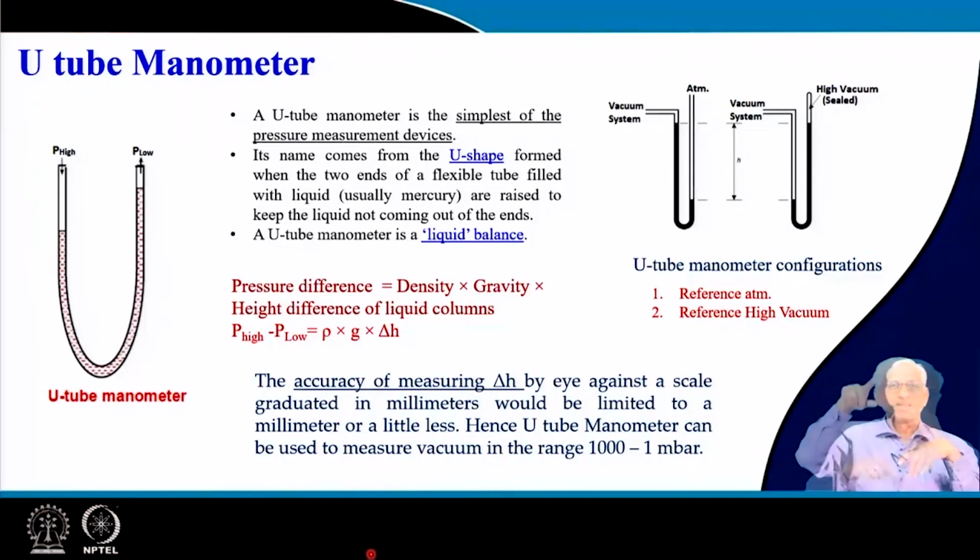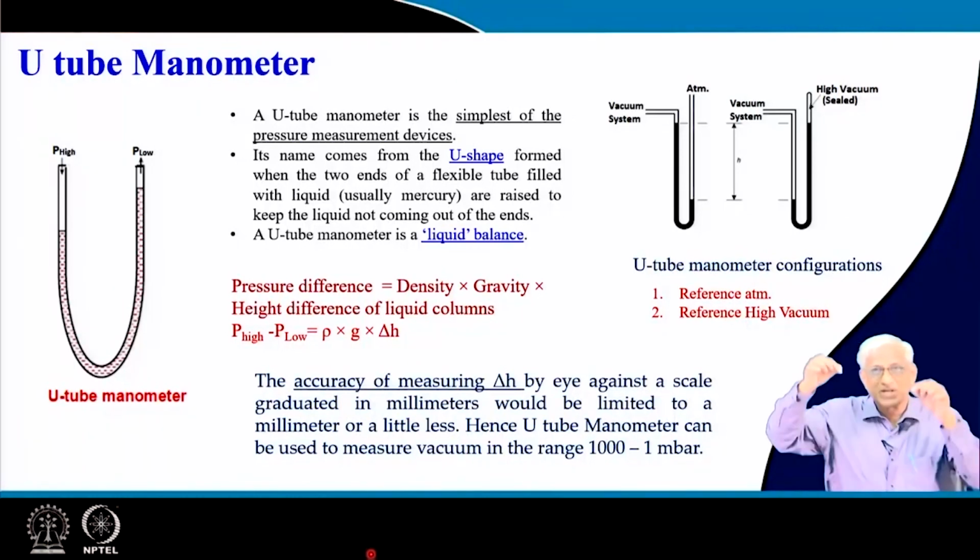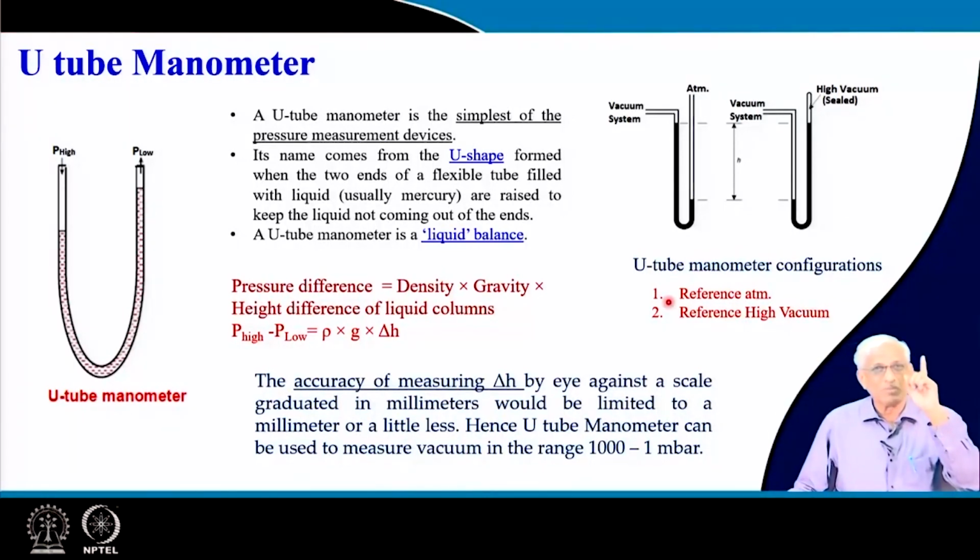The higher pressure side will be pushed. And why is the U there? Because you need to fill the mercury, which acts like an isolation between two pressures. Sometimes, when it is rising, some people call it a piston type of thing.